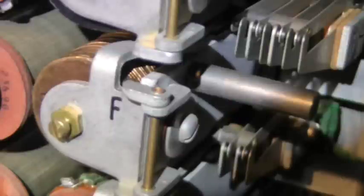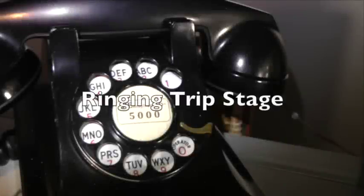The F relay is slow operating, and so the AC current flowing through its primary winding does not cause the relay to chatter. When the call is answered, the ringing is tripped immediately. Let's watch.